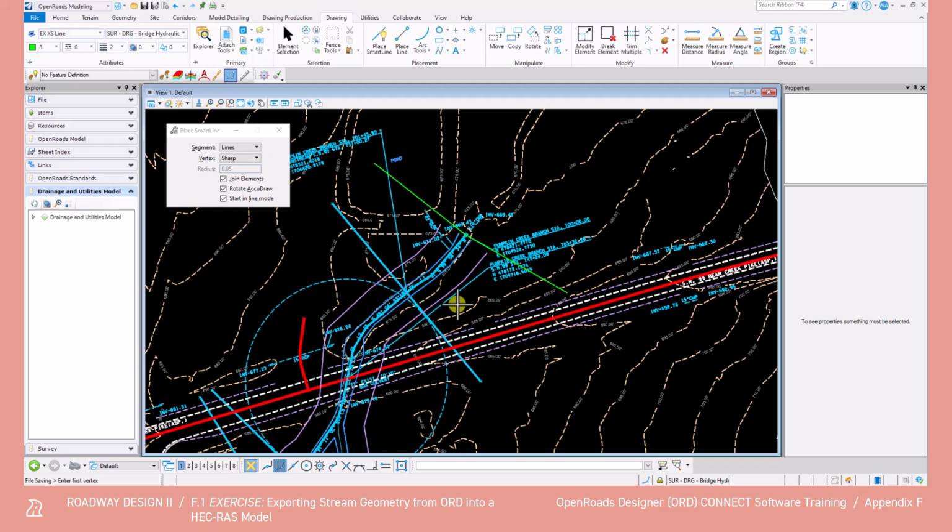And also note, do not place bounding cross-sections near the survey limits or culvert openings. The terrain in these areas may vary in accuracy due to the terrain triangle connection in these challenging areas.